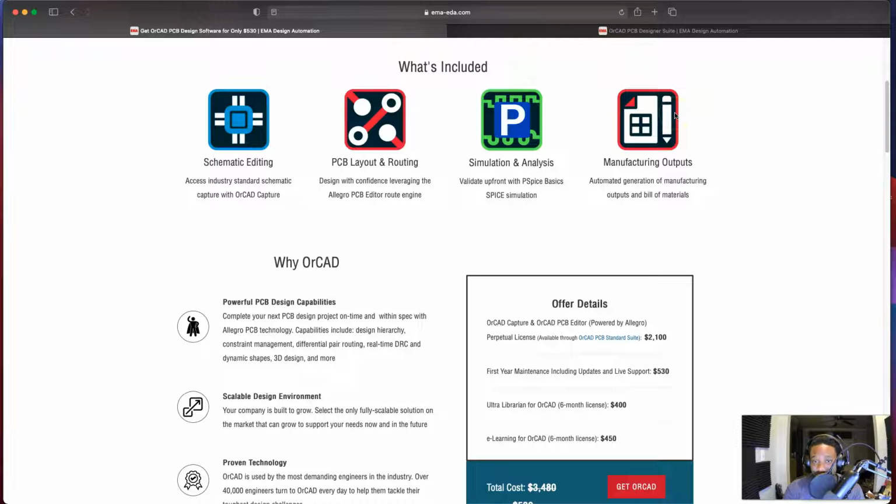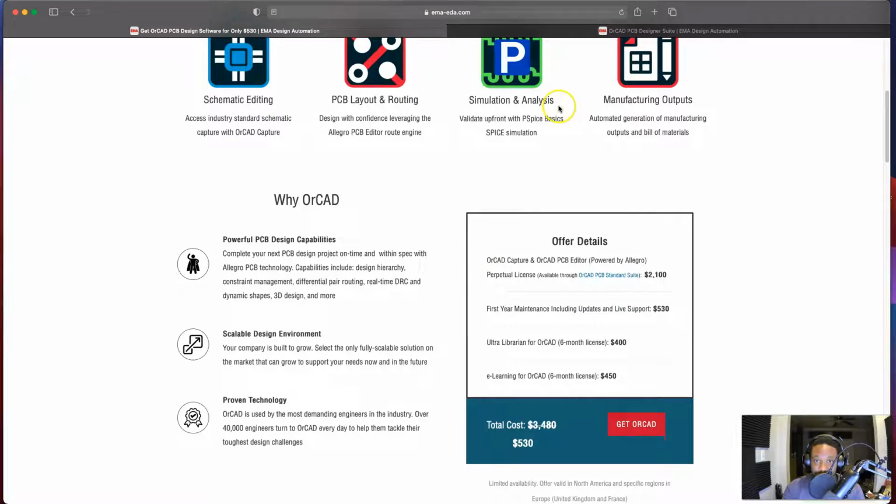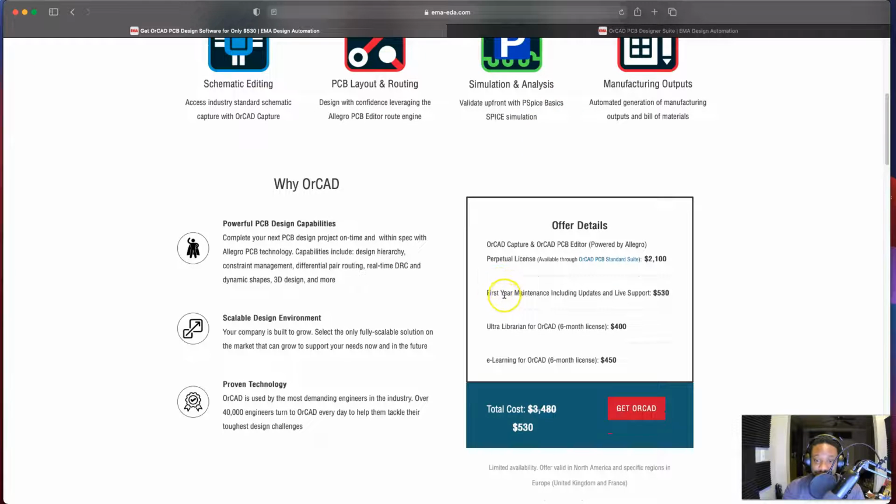Even if you don't set it up automated and you do it manually, there is a very important thing called design for manufacturing offering in the software. It's built into the software. So when you submit your PCB design for the first time to the DFM checker, I just did this last week, you get a first clean pass if you adhere to the design for manufacturer rules. That's just the software. Now let's get into the additional things.